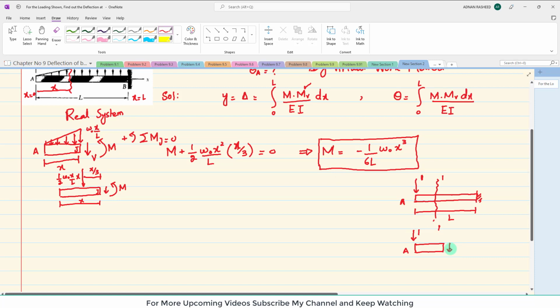When you cut the beam at section 1-1, there will be a shear force and a reaction moment, and let this distance be x. We apply the moment equation, that the sum of all moments about this section 1-1 should be equal to 0, taking counterclockwise as positive.